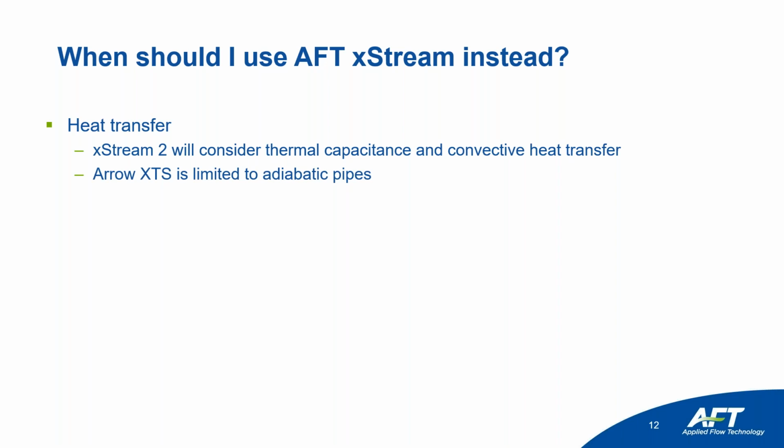So coming up, ideally later this month, but we'll see, certainly later in 2022, is the release of AFT xStream 2. It will consider things like the thermal capacitance of pipes. So imagine you're piping a super hot fluid. The pipes get really hot because they're touching the really hot fluid. And then when you change it to a cold fluid, the pipes are going to retain some heat and transfer it to the fluid. It will be able to consider that. And then it'll also consider things like convective heat transfer.